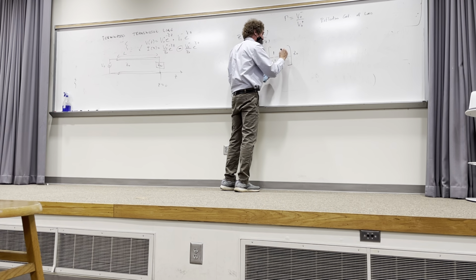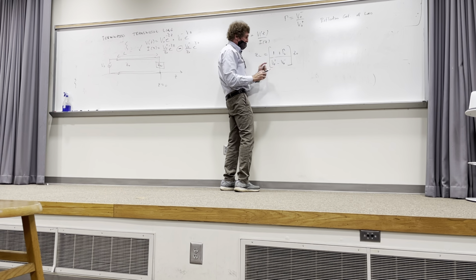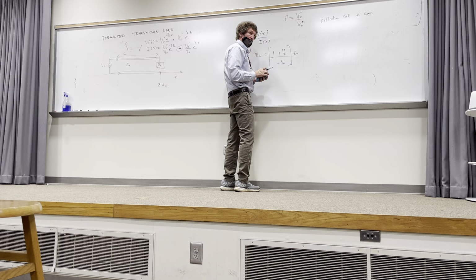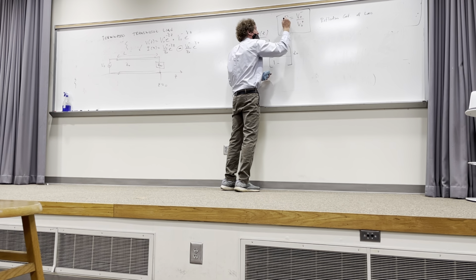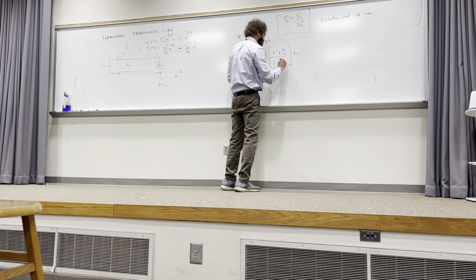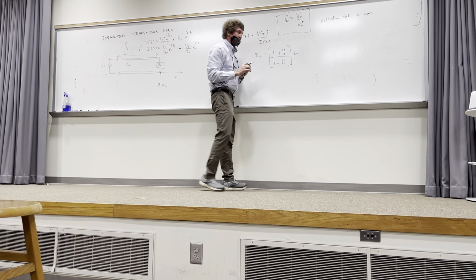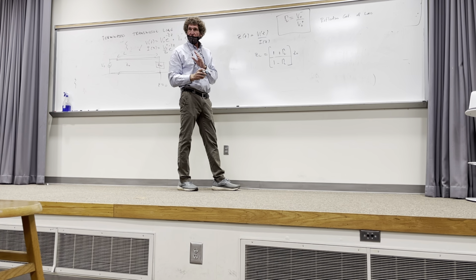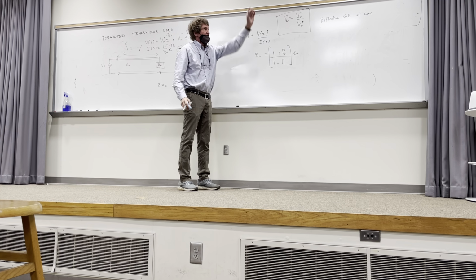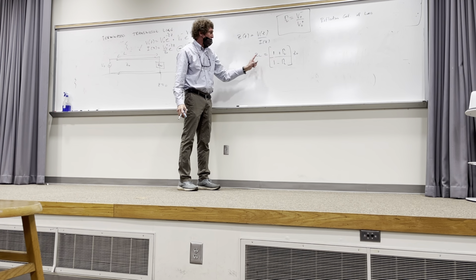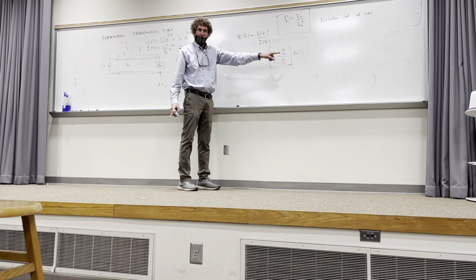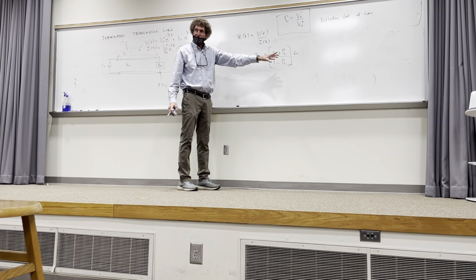That's the reflection coefficient at the load. Here I get V0 plus over V0 plus, or 1, and then this is minus gamma. This is actually at the load, and this is equal to ZL. Do y'all follow me? Now, I can manipulate this, and I know I'm about out of time. I can get gamma L in terms of ZL and Z0. Do y'all follow how I could do that? Don't write it down, just watch.